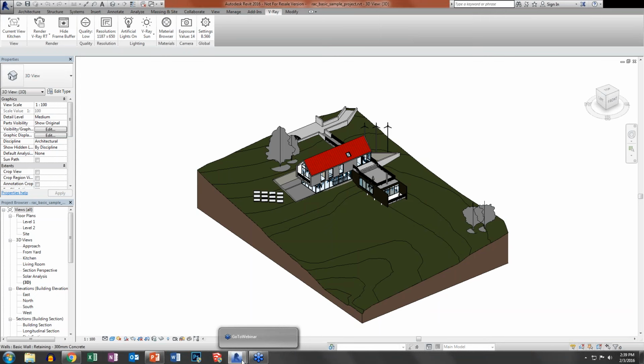Now this question, maybe you understand better what they're trying to say. Can I get from the render different renderings by channels, like object channel, color of objects, reflectance channel, etc., to use them? You can. In fact, that's built into the native V-Ray frame buffer itself. Just like you have channel support inside of V-Ray for Max or Rhino, we have it in V-Ray for Revit as well. Under the settings dialog, you can choose which channels you want to export. So yes, we do support channels.